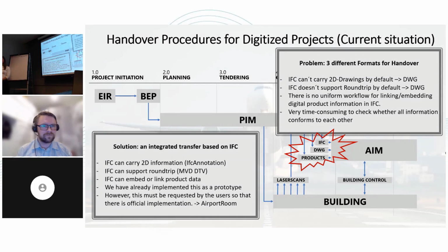they've also developed some very sophisticated automatic checking processes that run on IFC. Their solution is that they expect IFC, they run the checks, and if the checks are passed, they automatically generate the 2D drawings from the IFC so that they can then stamp and sign them.